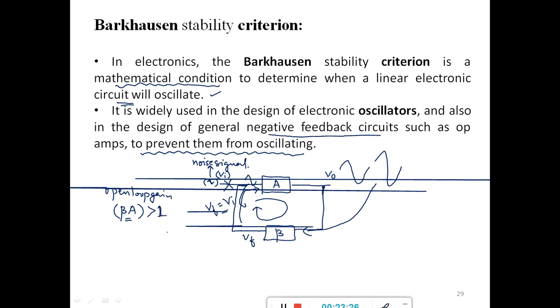So this sequence goes on continuing till a particular stage. The voltage further increases. After each and every stage or loop of the feedback, the amplitude of the output voltage is continuously going on increasing, because beta into A is greater than 1. This feature will continue for some time, and it will stop when beta into A automatically adjusts itself equal to 1 after some point of time.